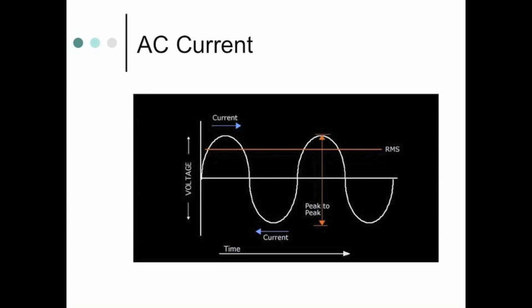Now in Europe, if we wanted to do 100 watts of work and we had 200 volts coming out of the wall, we would only need half an amp of current flow. Less current flow, meaning fewer electrons flowing through the wire, means that the wires don't get as hot, there's less friction, and therefore they can use thinner wires. And if that happens, then it's much cheaper and easier to do power distribution than it is to use thicker, heavier, more conductive wires. It dawned on me that there's a real reason why everybody chooses a different standard.